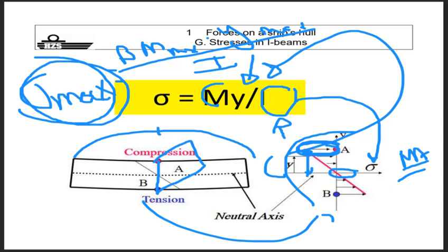And that goes behind the shear force and the bending moments. But of course, now I'm only focused on the static part and not the dynamic part. Dynamically speaking, we make it more difficult, and that's not the point, because on board you are only restricted to the static things. That's the only thing you have at hand as a captain. You do not have the dynamic part at hand. That has a naval architect to calculate prior to constructing a vessel, of course.